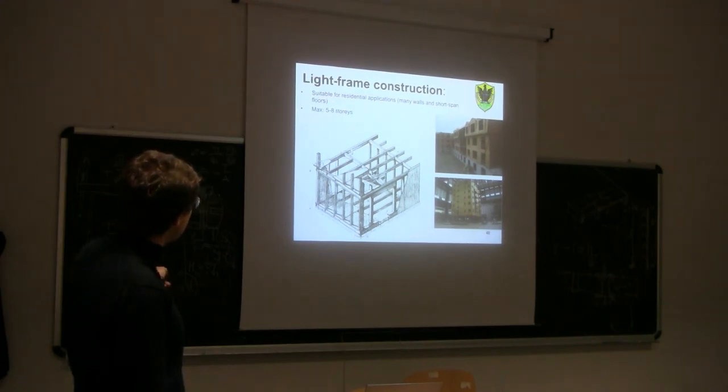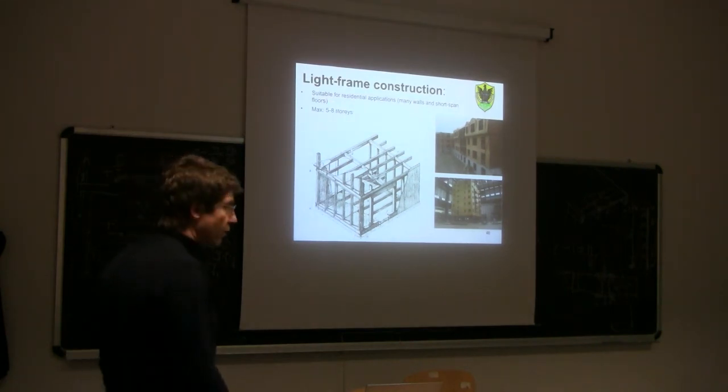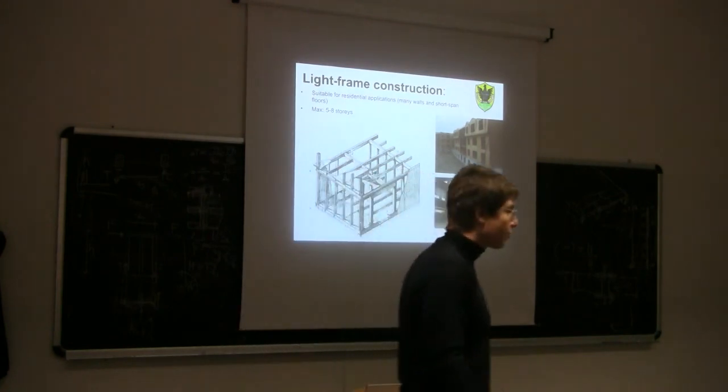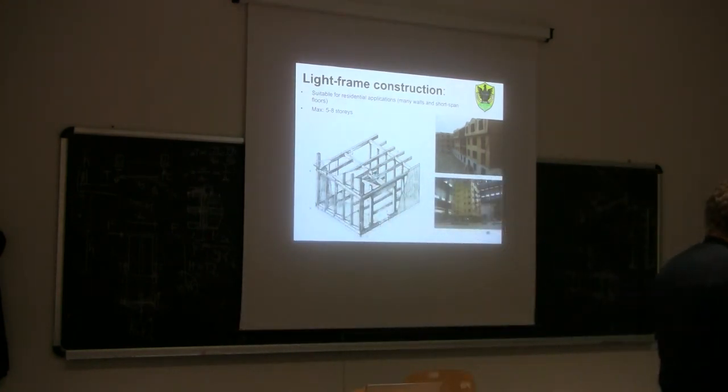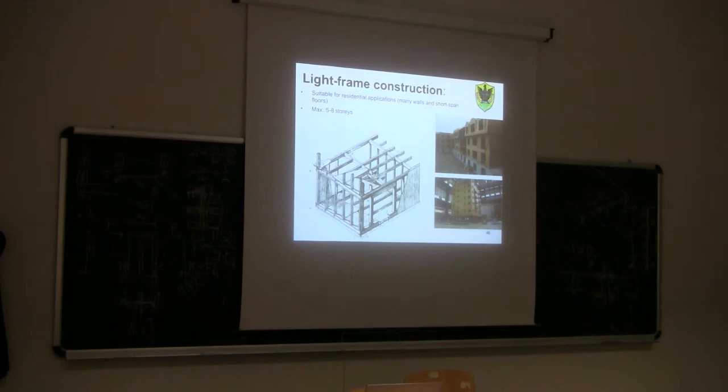So in this case, the maximum height is 5 to 8 stories. So 8 stories if you are in a non-seismic area, and 5 stories if you are in a seismic area. So for example, here in L'Aquila, you can't really build 10-story buildings using this kind of timber. You can get up to 4 or 5 stories.